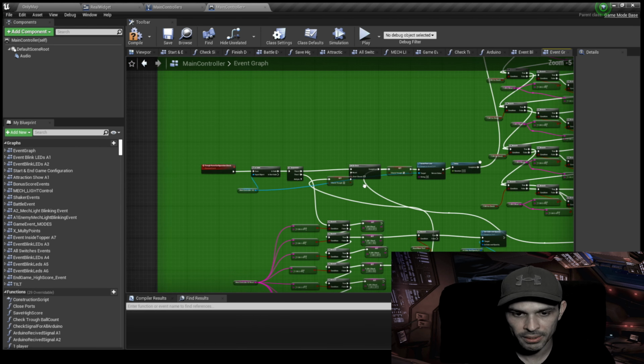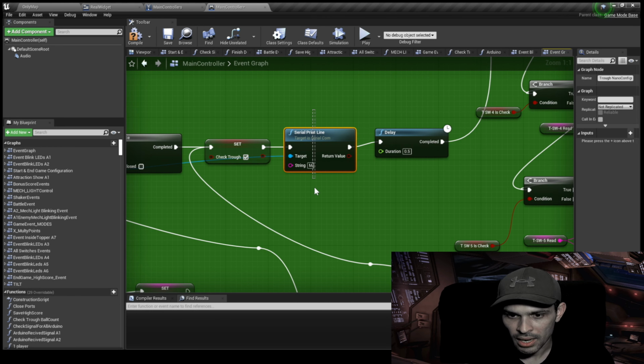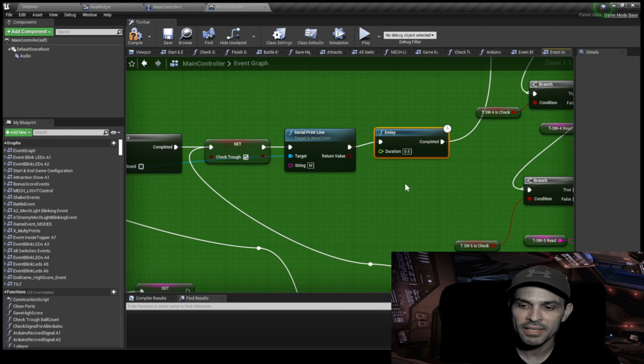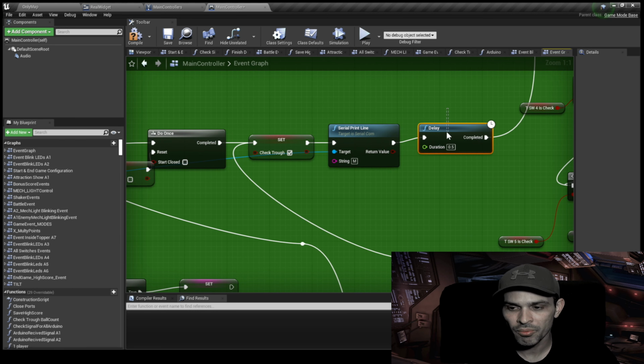And what is happening is this. When I call this, I send M and I wait 0.5 seconds. In this 0.5 seconds, the Arduino is already working. It has already done that. It takes approximately 0.05 to 0.1 second to do that tick. And that's why I put 0.5, so it's kind of instant.